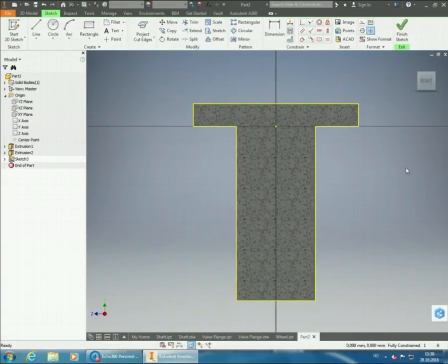Right, we're going to create the parts that are going to be extruding this way and the other way through the parts. But this is not circular. It's going to be more like a slot, because it's going to have the width of 60 millimeters, but it's going to have the height of 70. So it's still going to have a radius of 30 in the bottom and the top, but it needs to have a slightly straight portion in the middle.